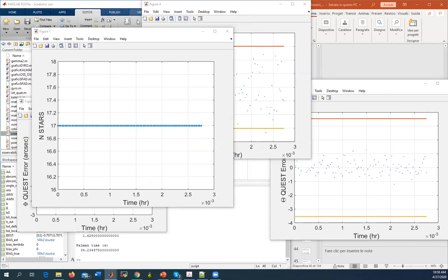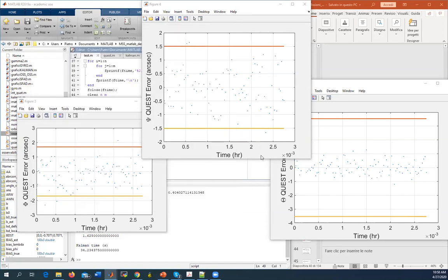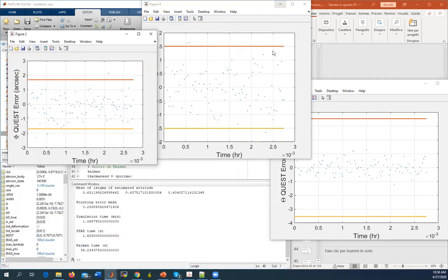Yeah, so basically we are assuming that the error is small, and so this is basically the representation of the vector components of the quaternion. So the first three components multiplied by 2. So this is what the Quest algorithm basically will provide you, if you are doing that correctly. So basically the error is inside this uncertainty level, and the important thing to understand is that all these measurements are independent from one another.